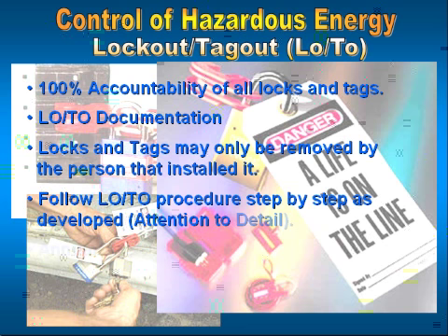Additionally, we've got a responsibility to develop the proper procedures to lock out and tag out the various systems. Once again, that will involve engineering. It will involve experienced employees that have worked with these systems. It may involve the developer of the product so that he can tell you exactly how to remove or isolate all energies that go into it.